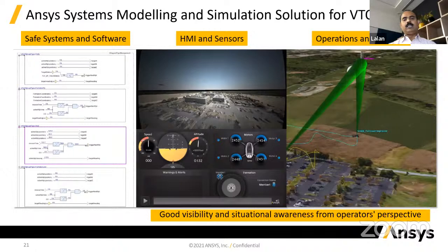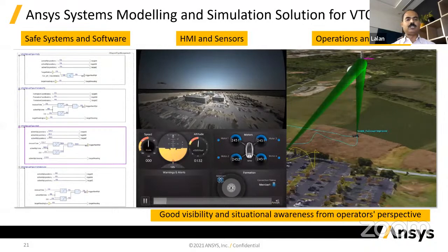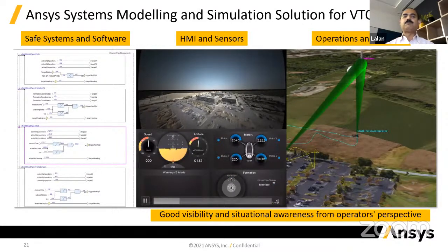So, in summary, what we discussed is that we developed the flight control software using the SCADE Suite, which is, as I said, the certified auto code generator for many critical software systems. And we created a display, which comes from the SCADE Suite, the SCADE Display.